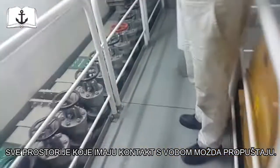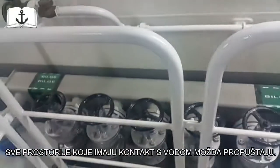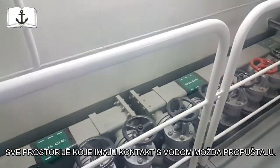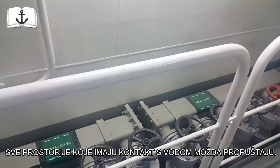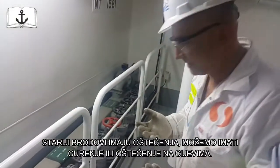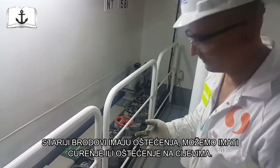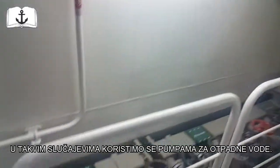You can mention maybe about the bilge system, that all the compartments on the ship, like rooms, whatever, that have contact with the water through the bulkhead, might be leaking. There are old ships, 30, 40, 50 years old, that can be cracked or whatever, then you're getting the water inside. Or we can have an internal leak on the pipework or the valve. Then you need to use each pump. We can always use this pump also.